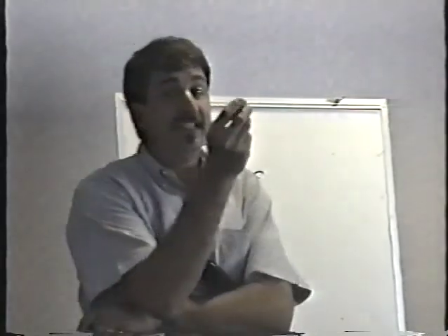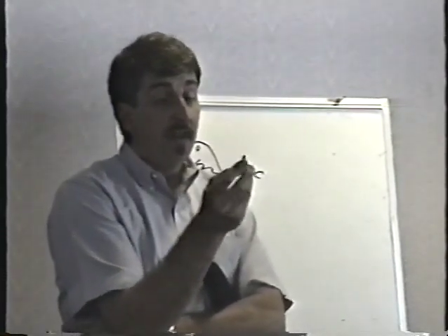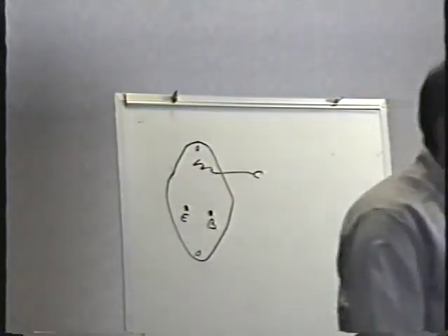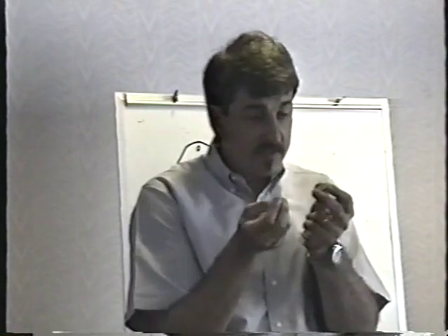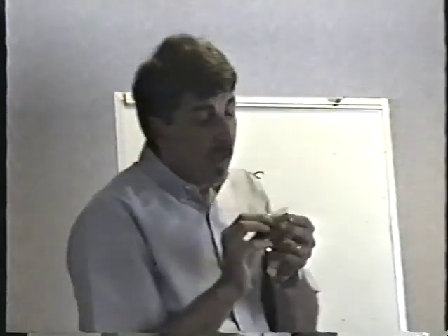Because the collector is the case of these things, it's electrically active. It's going to have some voltage on it most of the time. It can be anywhere from 12 volts to 160, depending on what the circuit is, so be careful. You will always see one of these insulators mounted behind it. When you change the transistor, you must make sure that you put the insulator back. You don't necessarily have to replace the insulator and put a new one in as long as it's intact.